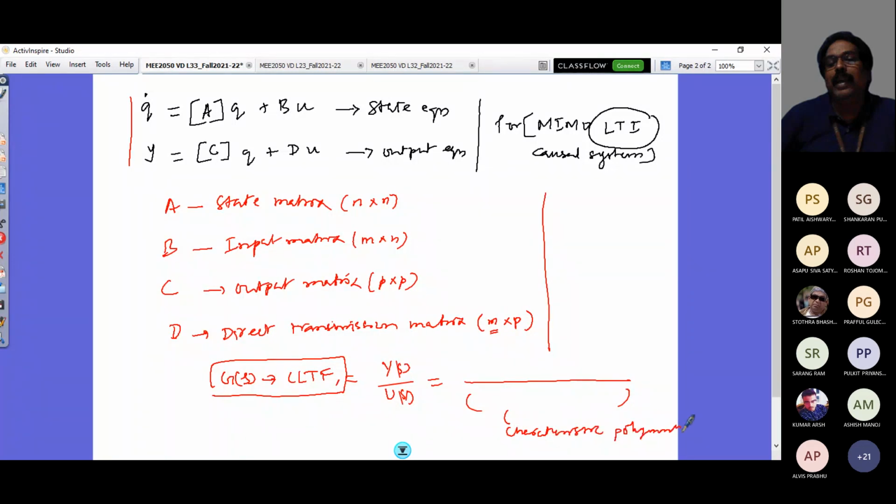So in the last class we have written, the order of this characteristic polynomial is n. The order of the polynomial in the numerator is m. So if m is less than n, then it is called a strictly proper transfer function. Like that all we have defined. So what is important here is this denominator polynomial is what is describing the characteristic of your system. So an nth order polynomial equation is what is defining nth order system characteristics.